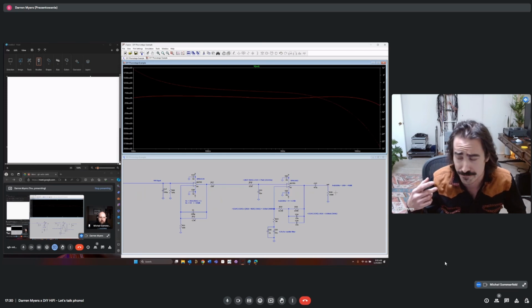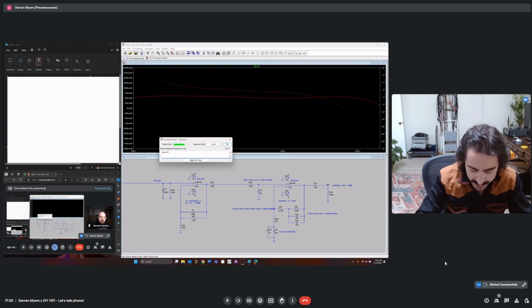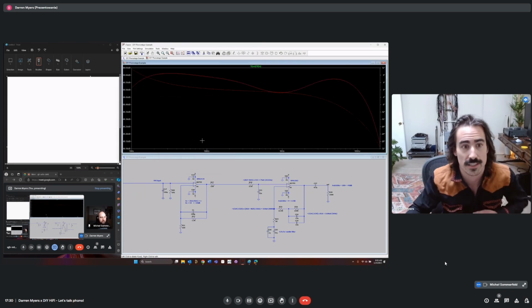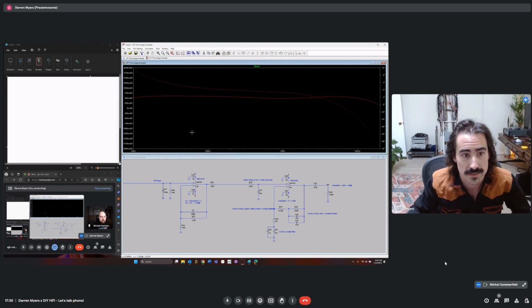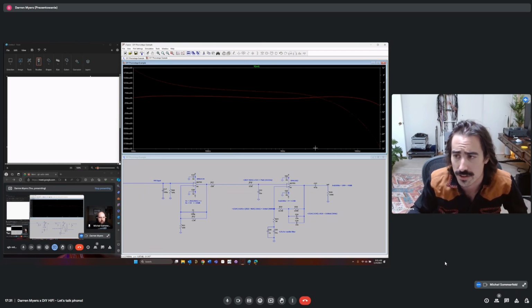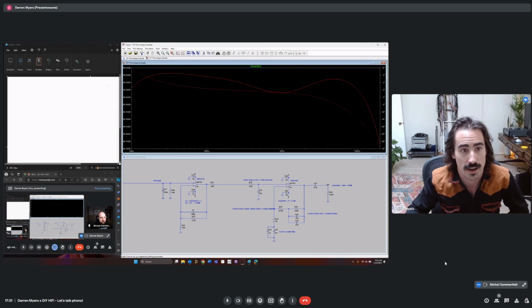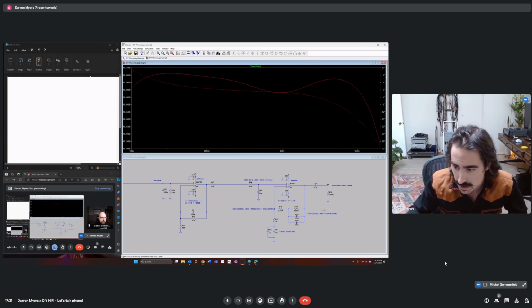But I just wanted to show you the end result here. We have V out divided by V in, our transfer function. Going back, adjust it, and we have, okay, because I have this saved, it won't save, I see. Okay, well, anyways, you can see the response is flat across the region. And when we look at the transfer function, we do have roughly our 40 dB.